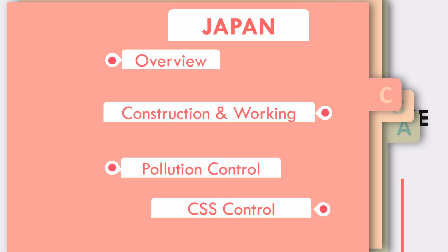However, the problem of pollution in stagnant coastal and freshwater bodies remains a challenge. The pollution affects fisheries, ecosystems, and recreational use and drinking water treatment. Let's talk about CSS control. CSS is combined sewer system. CSS serves around 25% of the population and 13% of a total of 1430 municipalities with wastewater service in Japan. CSS are designed to carry both sanitary wastewater and storm water in the same pipeline.